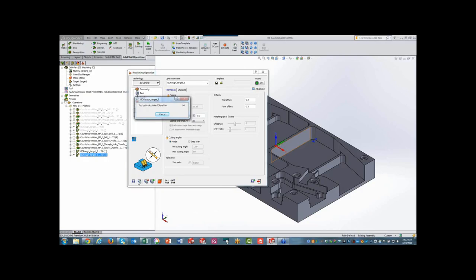Obviously, he picked here a smaller tool to do the rest machining. Right. So the tool that I picked now, thank you for mentioning that, is for going into corners where the previous operation could not go. I first used a larger tool to take out the massive amount of material, and then the smaller tool.